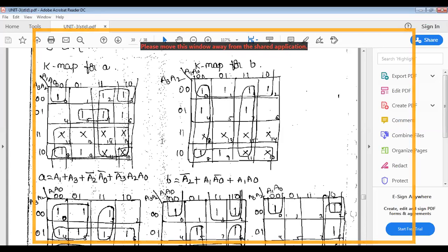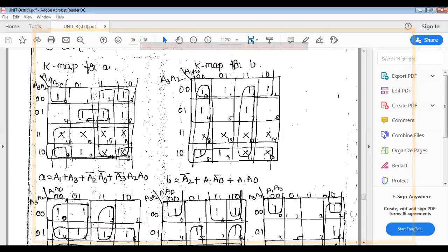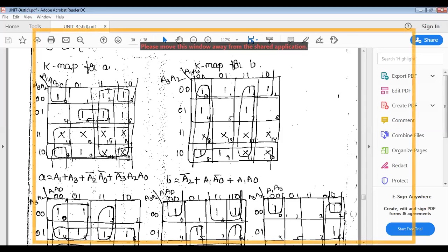Then after that, 8 and 9 are minterms. Using these minterms, under the 8 box combination we have the don't cares 10 to 15, that is 10, 11, 12, 13, 14 and 15. So 8, 9 is also covered. So 2, 3, 6, 7, 8, 9 are covered and the remaining are 0 and 5. Only these minterms remain, including the don't cares being covered.